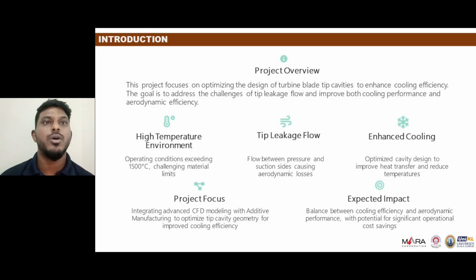For the introduction to our project, we all know gas turbine engines are vital power sources for aviation and electricity generation, operating under extremely high temperatures, often 1500 degrees Celsius. These temperatures surpass the melting limits of the superalloys used in the blades, making effective cooling essential for blade longevity and engine reliability. Cooling is achieved through a combination of internal cooling channels, film cooling holes, and the blade tip cavity, a small recessed region near the blade tip that plays a critical role in controlling airflow.